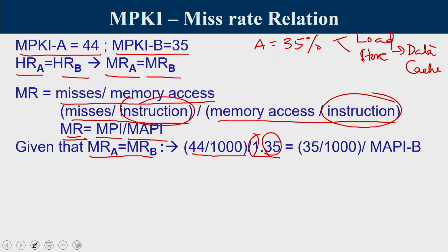Or if you imagine that out of all the instructions being fetched, none of them is a load or store instruction, then I go to memory only for fetching the instruction. So, memory accesses per instruction is 1, just once in the instruction fetch stage, and the mem stage won't be used. Let us assume that if all instructions are load or store instructions, then every instruction will go to iCache once to bring the instruction and to Dcache to access the data. So, since 35% are data access instructions, we have 1.35 as memory accesses per instruction.